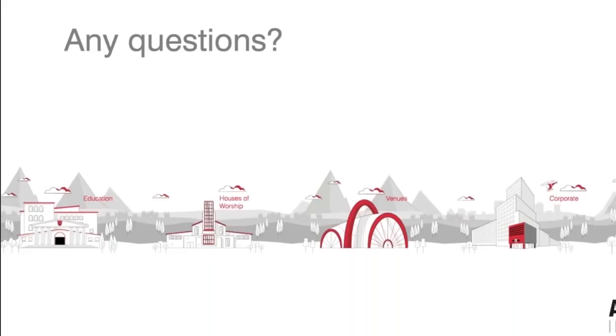For example, you can recall different scenes in the dLive system. And the purpose of those scenes might be simply to change the GPIO messages or contacts on an output to, for example, switch on a projector. If you're familiar with the dLive, you will know that you can filter anything else out of that scene. So that scene will only effectively switch on the projector, and with a button in custom controller, I can do just that. So there are multiple ways of interacting with third-party devices.